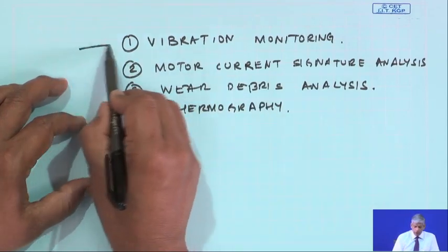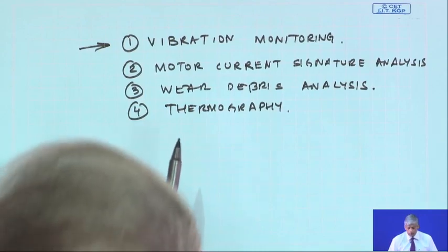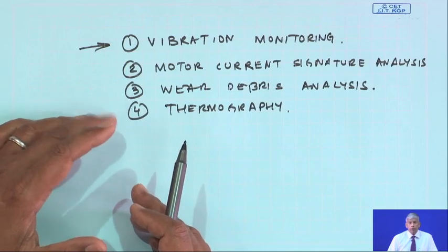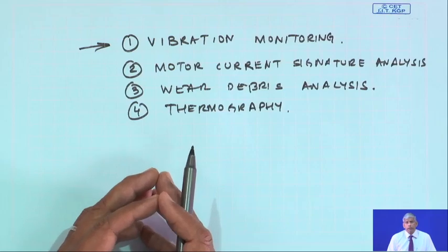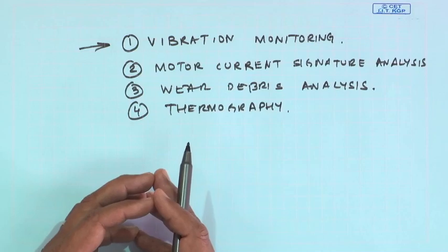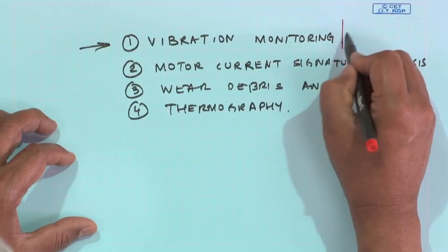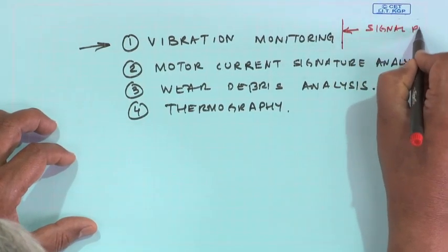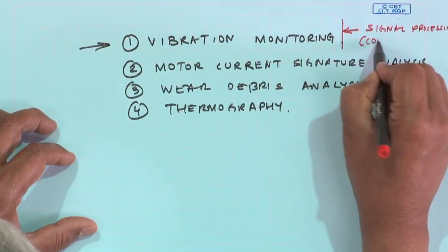So, traditionally vibration monitoring was being used to measure the vibrations of a gearbox, and analyzing them in the time domain, in the frequency domain, we can find out the faults in the gearbox. And while discussing subsystem analysis, I did mention how subsystem analysis can be used to find out and identify the defects in the gearboxes, and then vibration monitoring with some signal processing technique, like coherence analysis.